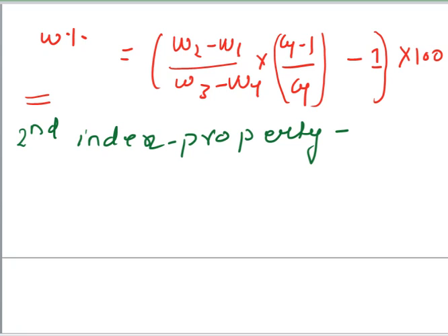Okay, so we will discuss in this slide. To determine the water content we anyhow require specific gravity. So obviously while conducting Pycnometer method, we combiningly do both experiments. First we do the experiment to determine the specific gravity, then we conduct the same experiment to determine the moisture content of the moist soil.